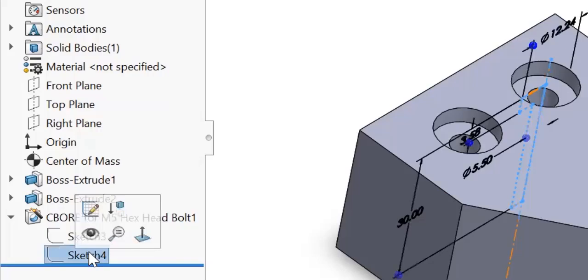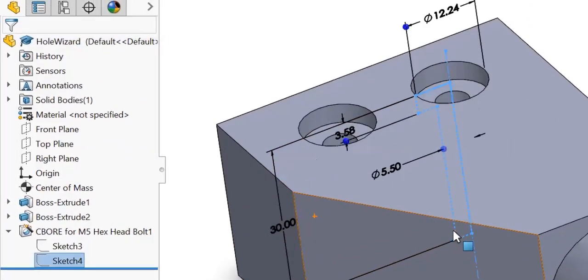And the second one is what the system creates as the section of the hole. So internally, it creates this section sketch with specified diameters and dimensions based on the standard you chose, and makes a revolve cut. Okay, and you do the same thing in here.